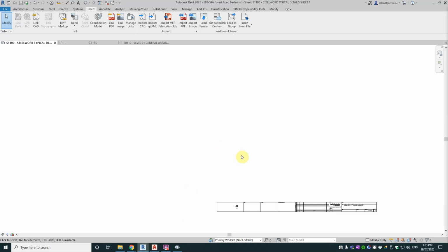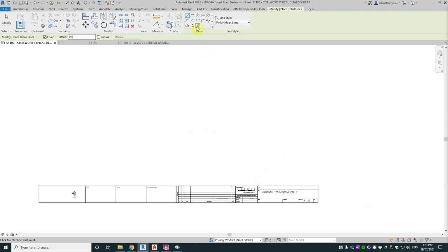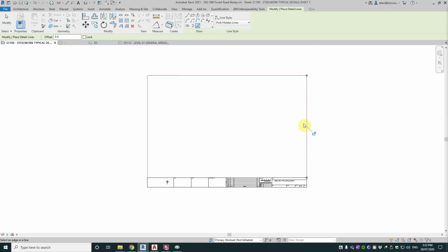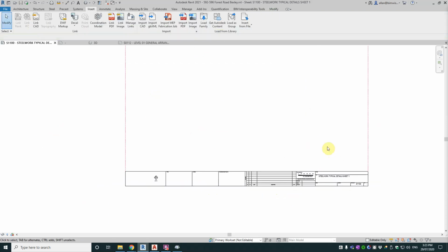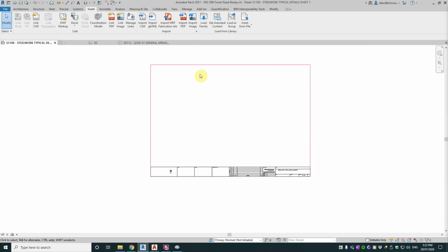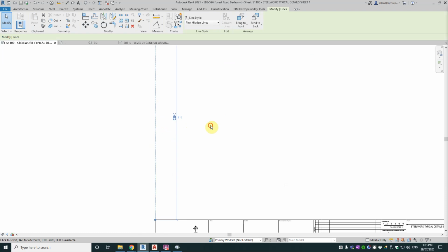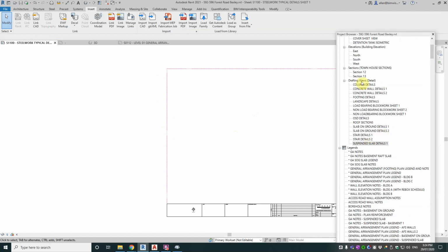Now we go back to Revit and we've got our sheet in here. Now it's borderless because that is the funky way to work now, just makes your drawings look great. You don't need to have borders around anymore with just PDF deliveries. So we have our title block here. Now I've just put those pink lines there temporarily to frame it so you know where it is, and see what this says there, 529. So the other one was 5290, so 10 times, so that's the scale. So what we need to do to bring in our detail from AutoCAD now is to create a drafting view.